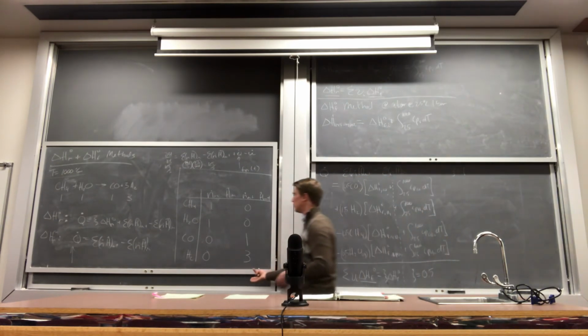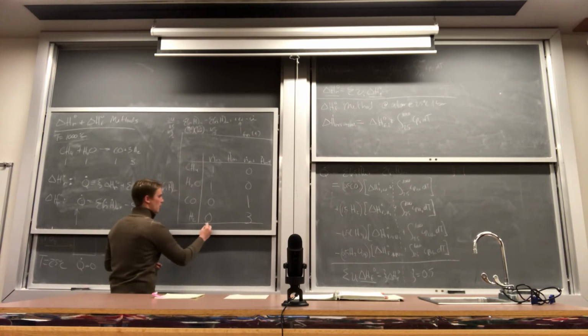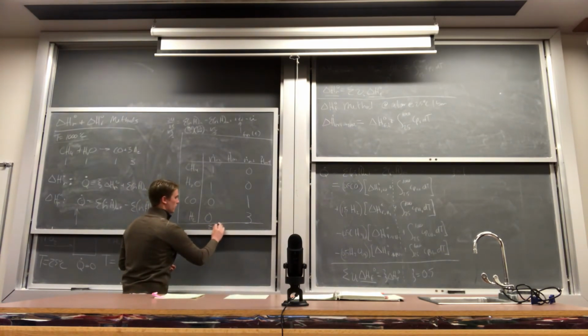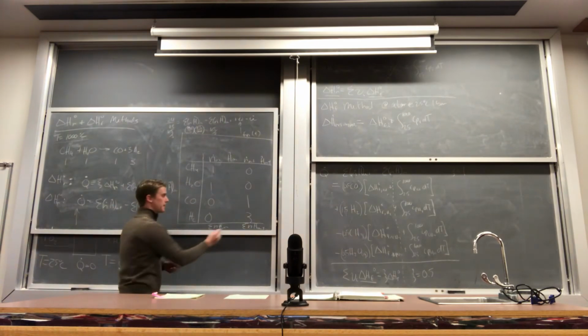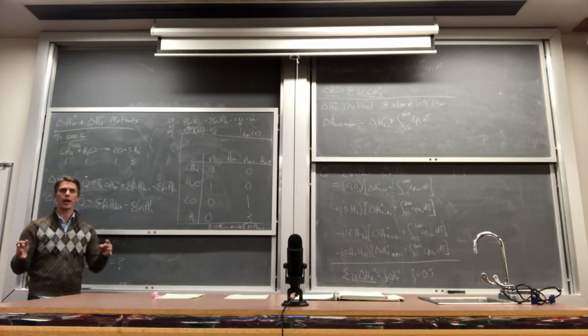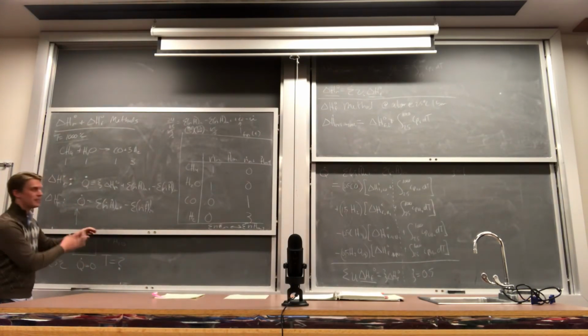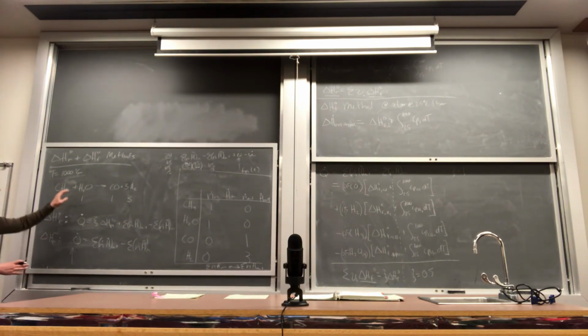And so at the bottom here, you're going to have some number for the summation of nH in, summation of nH out. And the difference between these two tells us our Q. That's what we're calculating here in our energy balance problems. But we can take this exact same tool if we designed it right. And what we can say is instead of knowing that our outlet temperature is 1,000 degrees C, we can solve for it.